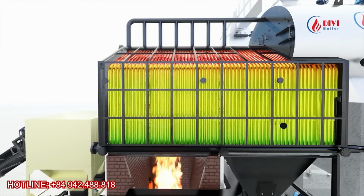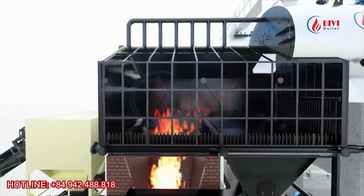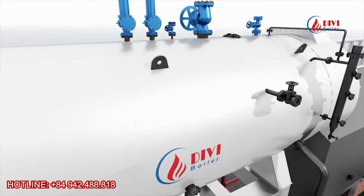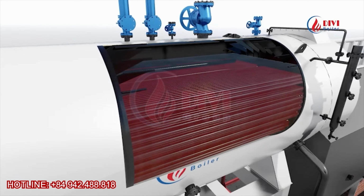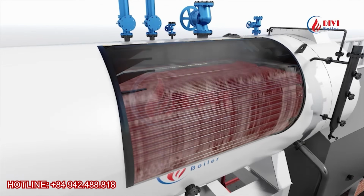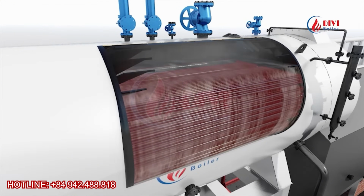One of its biggest advantages is its excellent heat transfer efficiency. That's because the flue gas flows through many small fire tubes. As the flue gas is divided into many smaller streams, the contact area between the hot gas and the heat transfer surface becomes much larger. This results in highly efficient heat transfer.